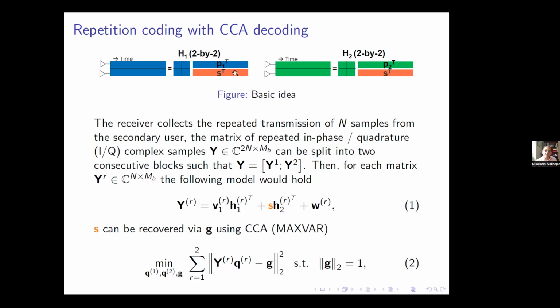The orange signal below it is the secondary signal that you want to transmit over a short distance, right? In the same band at the same time as the FM or other, let's say, legacy service that is using that part of the spectrum. Now, because of superposition of electromagnetic waves in the air, what your first antenna receives is a linear combination of the FM signal, or whatever it is that the primary transmitter is transmitting, and the secondary, the orange transmission that you are transmitting, right?